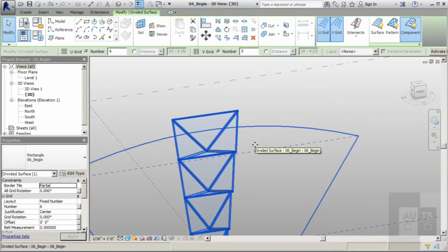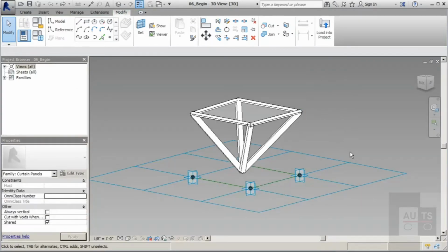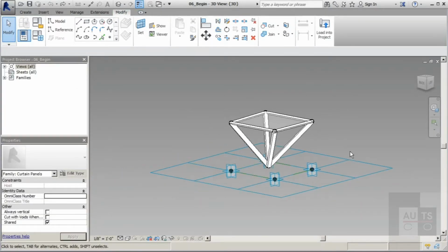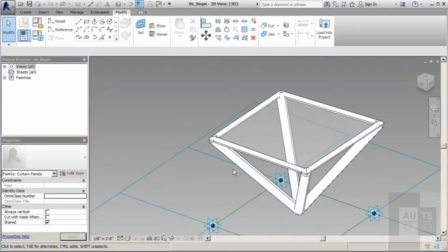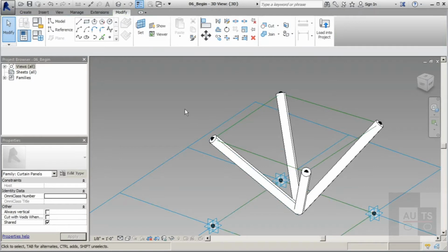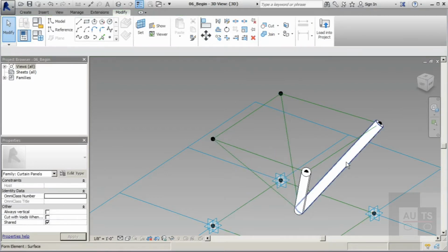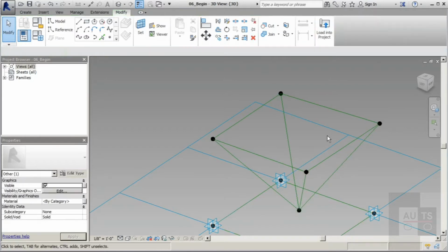So I'm going to Control Z out of here really quick and get back to my basic mesh, but then I'm going to Control Tab and go back to my form. So let's make some adjustments to our form here. So we can go ahead and get started with the easiest one here. We'll start with our form here, and I'm going to highlight that form and get rid of it, and we'll get rid of everything on there. And we'll go ahead and get rid of these guys as well. So I'm going to get rid of that element, get rid of this element, and this element. So I'm going to try to create my struts first, but I'm going to reduce that dimension. We'll reduce it to about 3 inches. Originally, we had it with a 5-inch radius, so we'll switch that to 3.